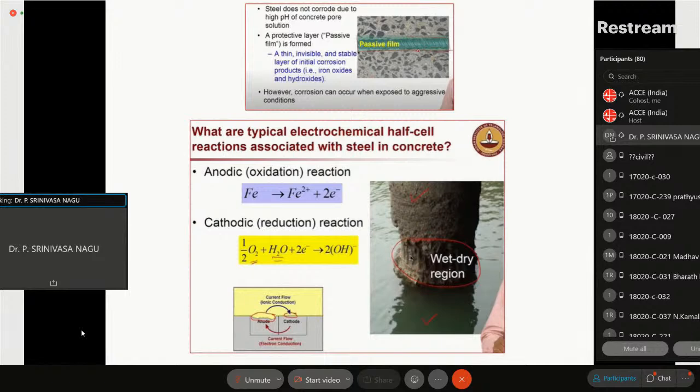The shield could be broken by an external agent of inhibiting nature through the cracks of the concrete, water or other chemical intrusion, even the pore liquid within the concrete gel, or within the passive material, as I told you, small cracks, or even phase differences, ferrite phase, martensite phase. These are metallurgical terms, you know. There will be different phases. That is the crystal structures. The metal is having a crystal structure in an amorphous matrix.